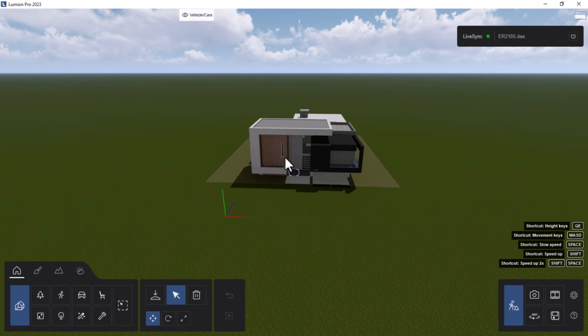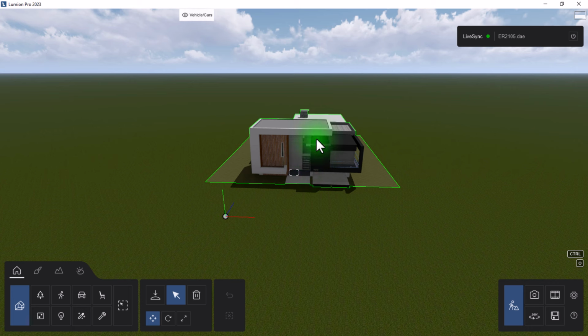So the position of your model within Lumion is based on your 3D modeling program, and this corresponds with all 3D modeling programs. It's more like your 0,0 origin point. So when you are creating your project, make sure you don't create it far from this point. It's good to have your project around this point for navigation purposes, most especially in third-party programs. Even in your 3D program, it's also important not to move away from this point.